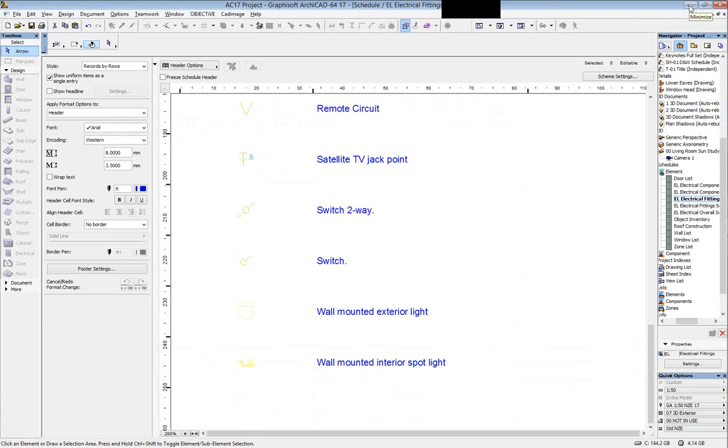Okay, and the last one we developed, which I'm only going to discuss briefly, is called the BCF tool, and this is BIM Collaboration Format. This was designed to allow ArchiCAD to communicate with a checking software called Solibri. The idea is this software can look at your model, figure out if you meet code, company standards, and different requirements. And if there was a problem, the BCF tool allowed you to send a message back to ArchiCAD and say, this isn't right, please fix this clash or this error.